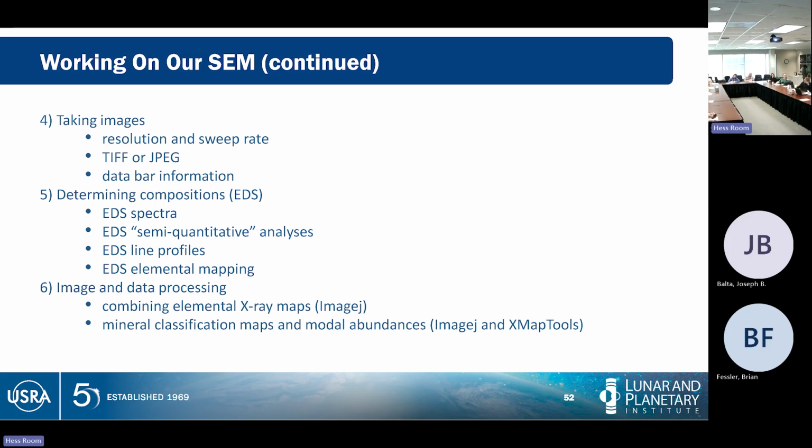Settings that you can control. The vacuum level, we'll talk about that in a second. The accelerating voltage, we've talked about this. This is the energy that drives the beam down. The current, meaning our aperture controls that, as well as how much energy is pumped into this. What type of imaging do we want to do?